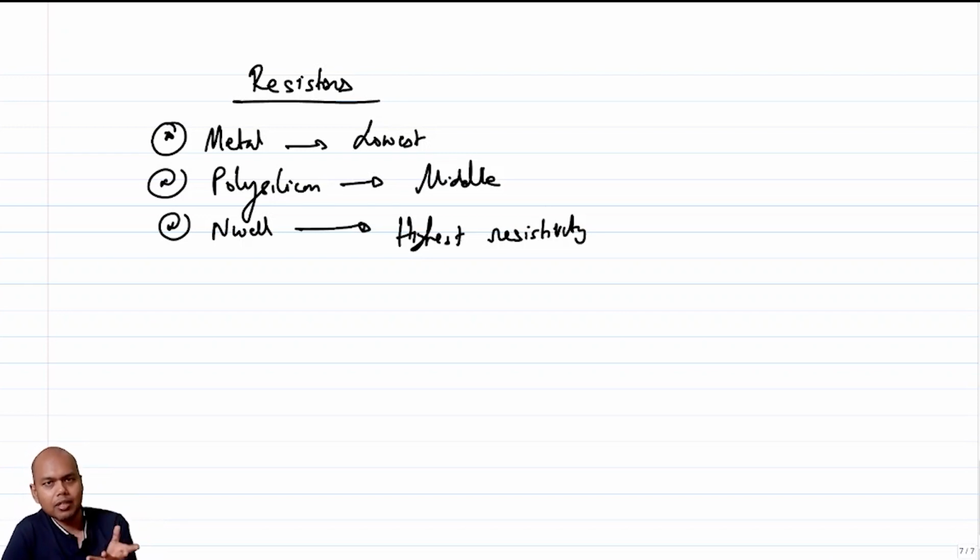The core principle of making a resistor is that you have a lattice, right? You have some piece of silicon or a piece of material, you have a lattice, and as carriers flow, the question is how much hindrance the lattice provides to the carrier flow. Now, if you increase temperature, the lattice also vibrates, and you have a lot more hindrance, and hence your resistivity can change.